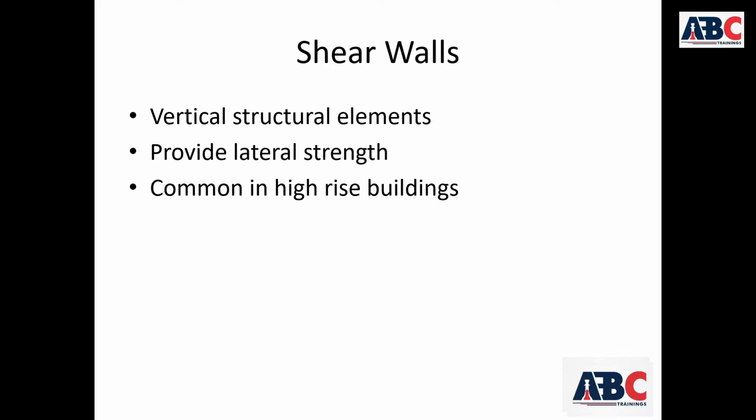Why are shear walls required during an earthquake? Buildings experience strong lateral forces. How do shear walls work? Let us understand how a shear wall functions. When lateral loads act, the wall behaves like a vertical cantilever, and it resists bending and shear force.